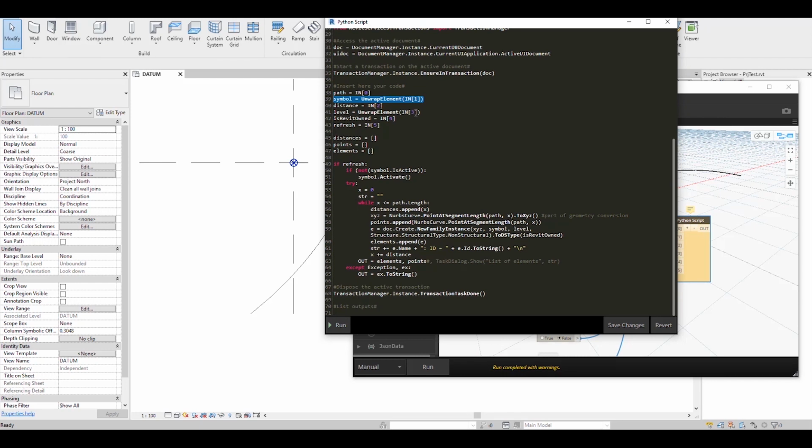But to be able to access the API, the Revit API and the objects, we need to encapsulate these objects. And so what basically Dynamo does is to use specific types, and to be able to access objects that are straight coming from Revit, we need to do what is called an unwrapping of this object.